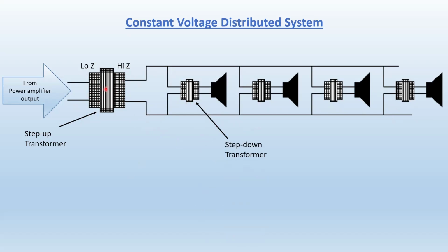This one, you sometimes have to use both hands to lift because it's heavy. And this one here, you can just close your palm around it. Step-down transformer. On this side, it has the high impedance to match the high impedance that is being shot out of that transformer. And it transforms to the low impedance because the speaker wants to see 8 ohms.